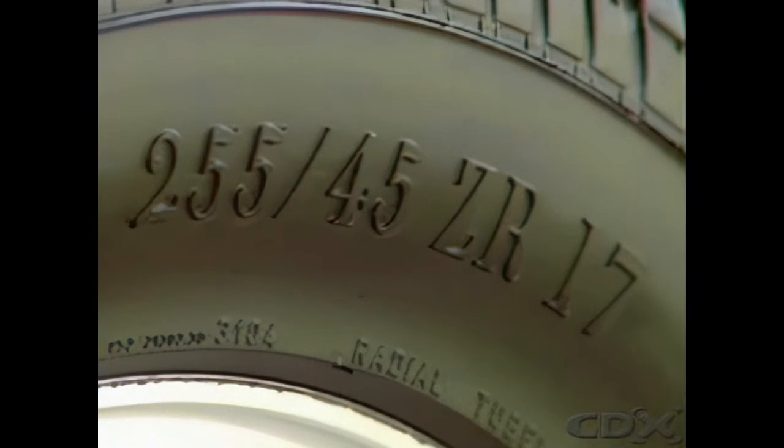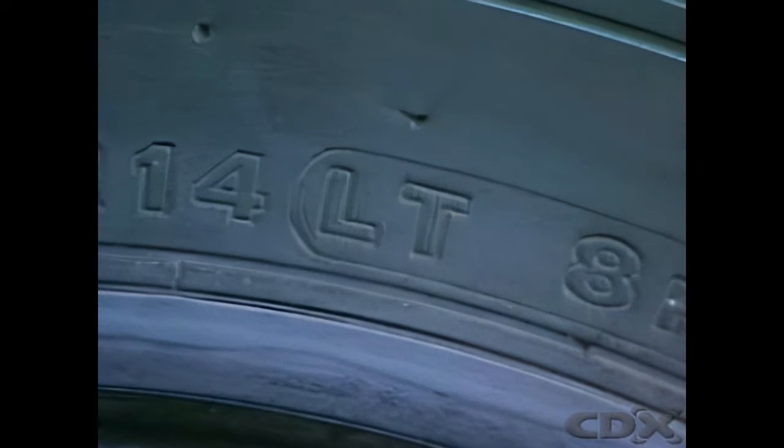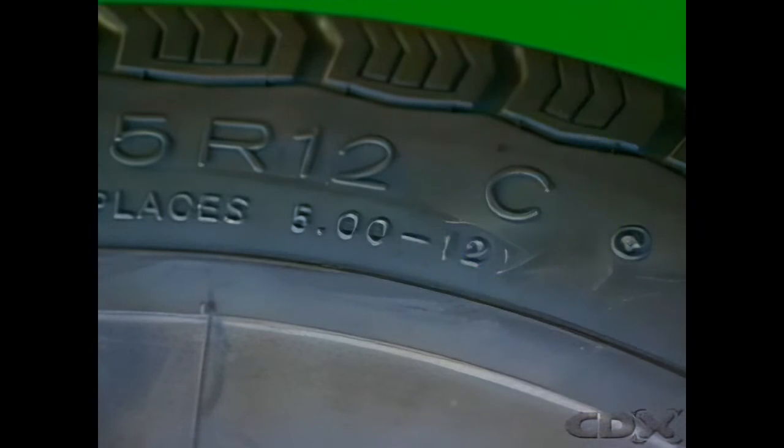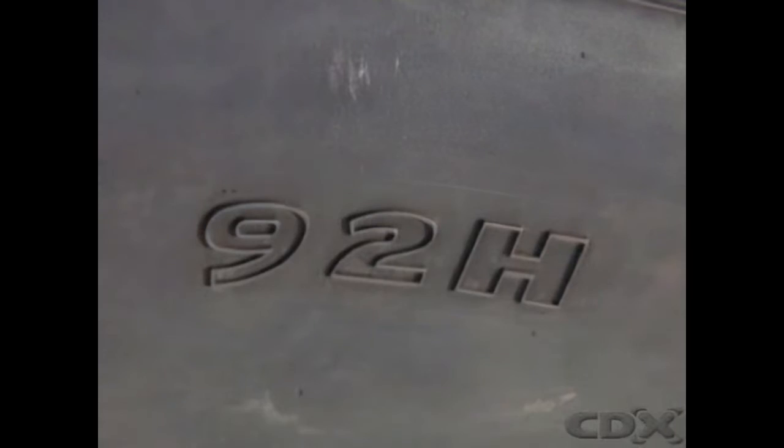Although tire markings may remain traditional, say 255/45 ZR17, there is a worldwide move towards an ISO metric standard, which uses letters: P for passenger, LT for light truck, C for commercial, and T means temporary use as a spare wheel. The tire may have a load index number, indicating the maximum load a tire can carry at the speed indicated by its speed symbol, which follows the number.